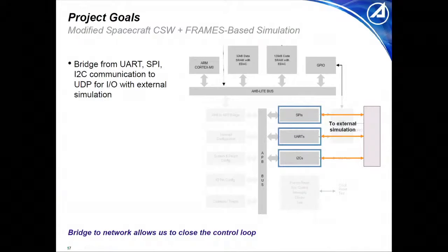One thing I want to talk about a little bit, I don't know how familiar people are with QEMU. There are I2C bus emulations in QEMU. It's all baked in, but really what happens is when you write to an emulated I2C peripheral in QEMU and it gets put onto the emulated I2C bus, that all stays within QEMU.